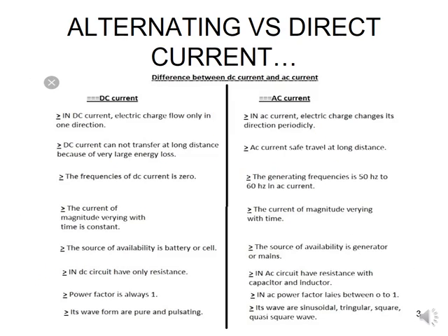So the major differences between direct and alternating current are as follows. Firstly, in DC, as we stated already, your current only flows in one direction, compared to AC, which changes direction periodically. On your DC, you are unable to transfer power over long distances, as you get very large energy losses, or rather resistance losses, on your line.